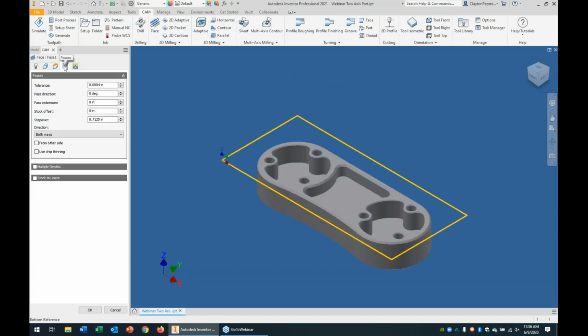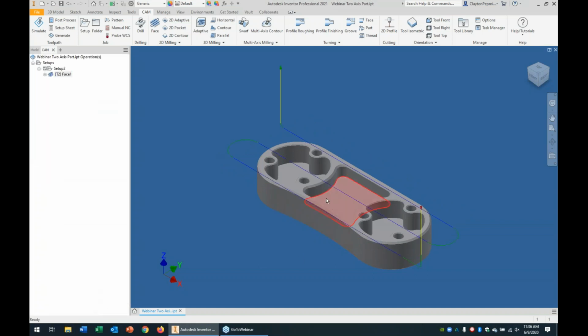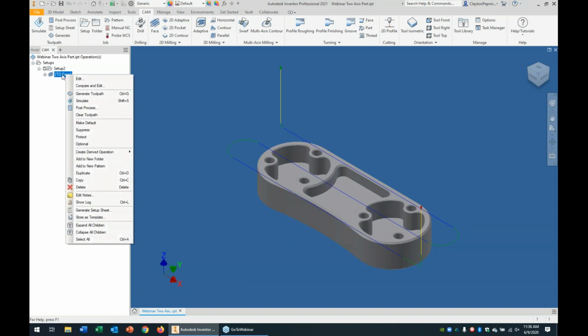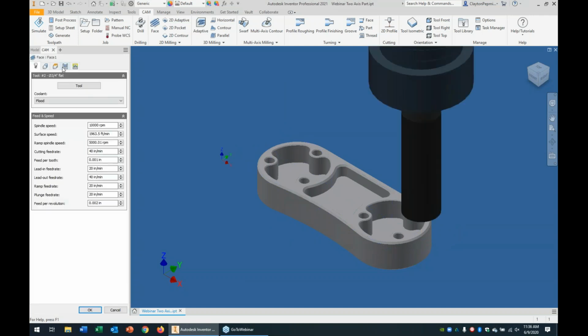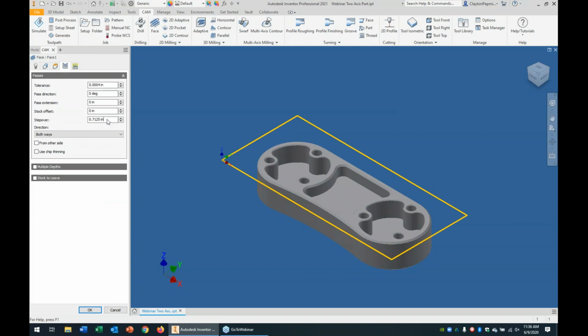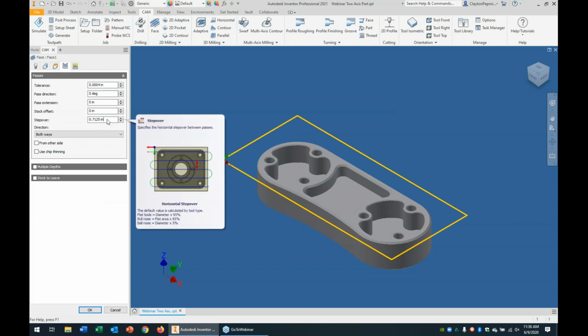The 4th tab is what I call the control tab. This is where you start getting into the nitty-gritty of what you're machining. So give me an example. Let me just say, okay, I didn't change anything. There's our toolpath. Let's say I don't like how much of that tool is being used for that cut. It's using like 95% of the tool. I just double-click, go to my control page. It's using, by the way, there are defaults here.